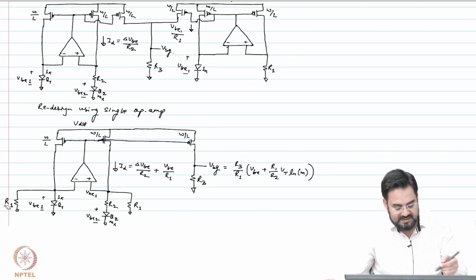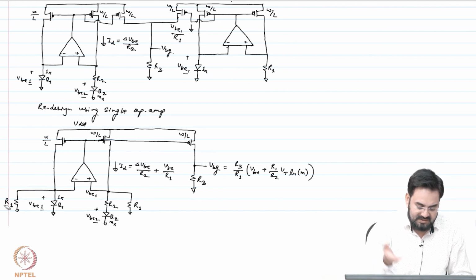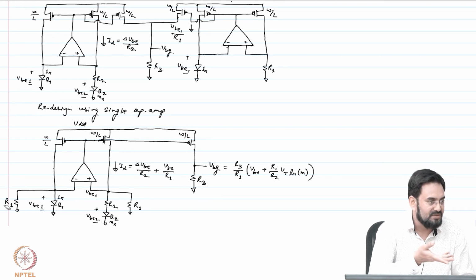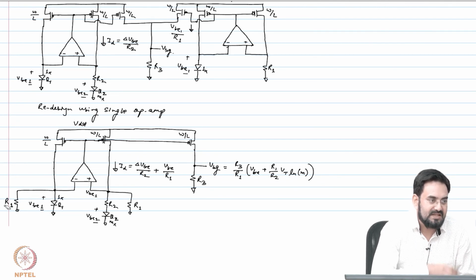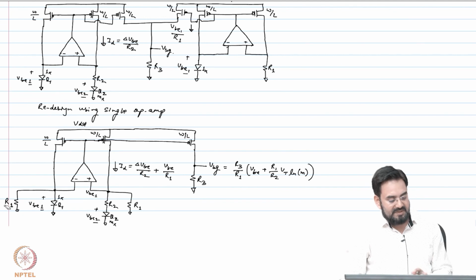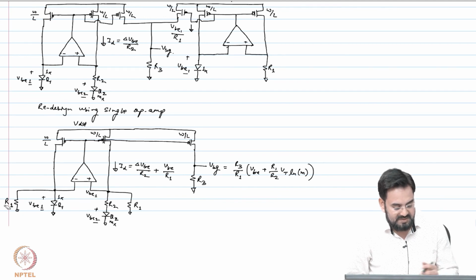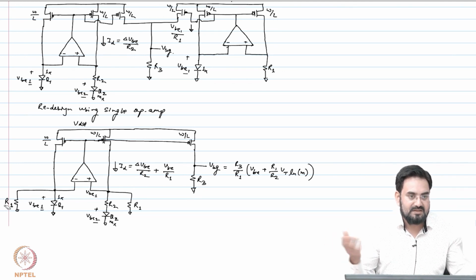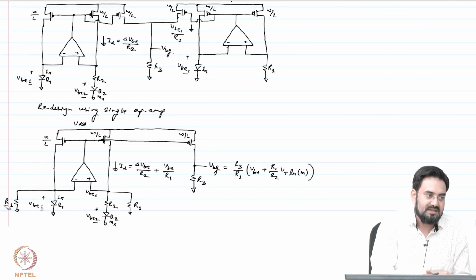Still we get a very decent accuracy with this, and if you are much more concerned about this VDS mismatch, if you have a larger VDD, you can always use cascode. So with the cascode you can fix that, but without cascode obviously there will be some error due to that, which means you are forced to use these PMOS sizes, channel length much larger, so that you can reduce the effect of your channel length modulation.